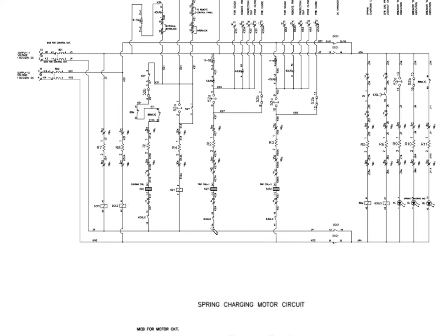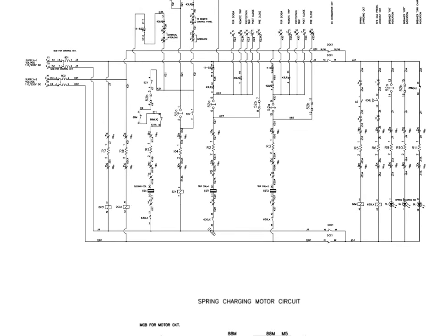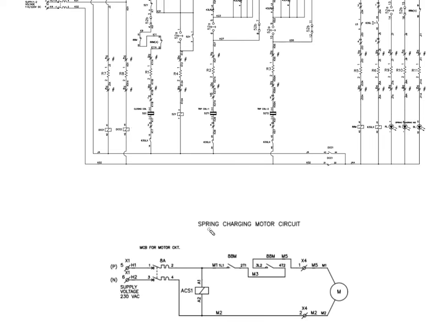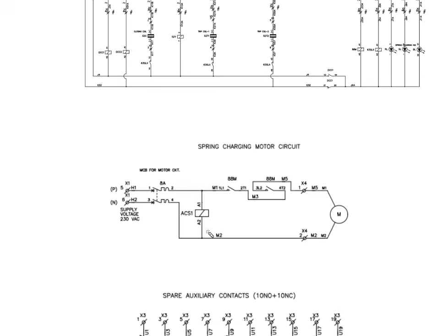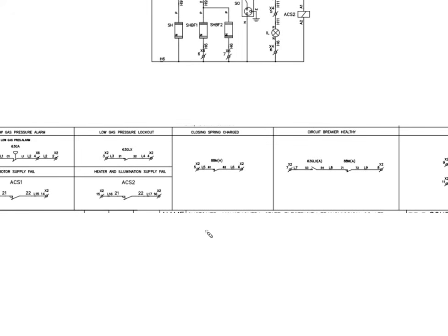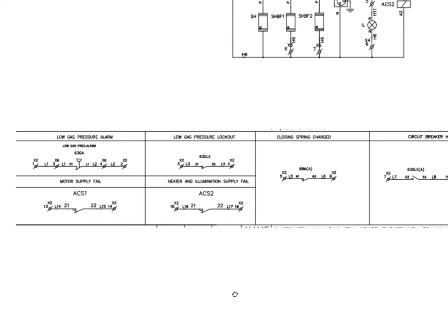Those indications are motor heater and illumination supply fail. I don't think we need this indication. DC supply fail, this we can use, we can wire it up.